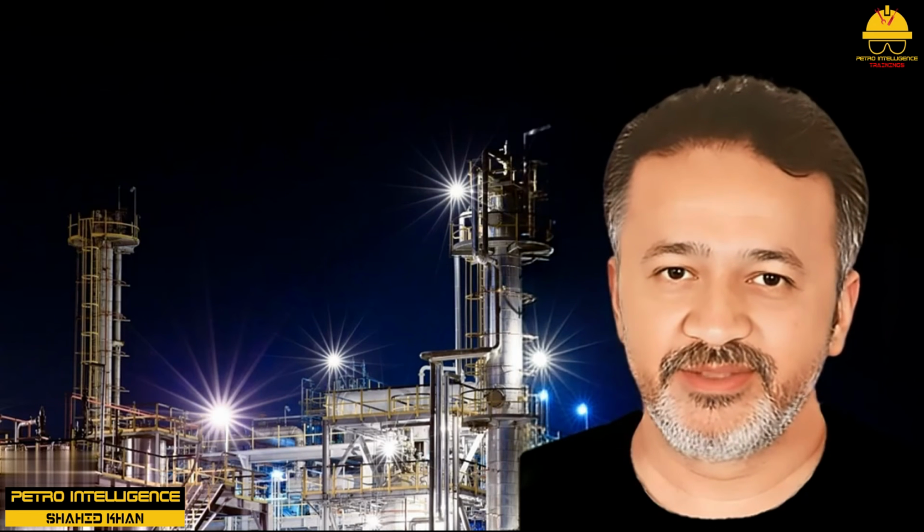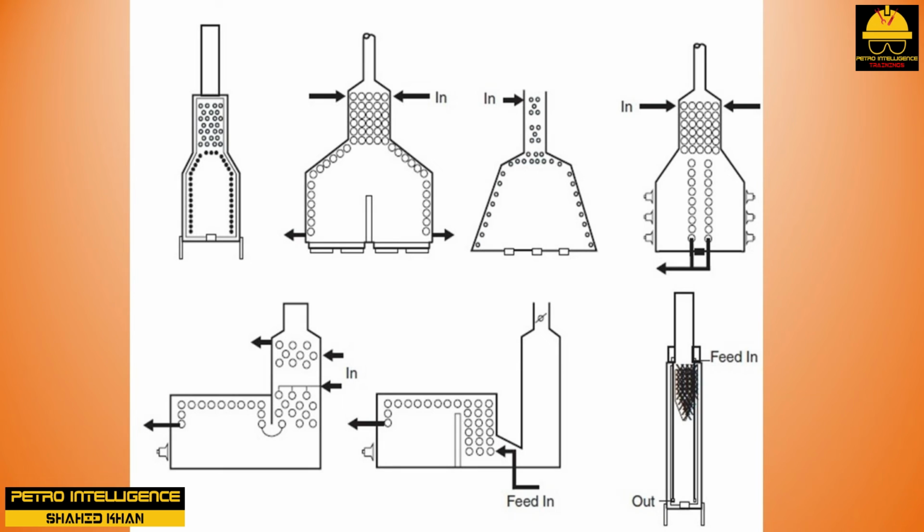Reaction furnaces. Reaction furnaces are simply fireboxes containing an arrangement of tubing through which the reactant stream is passed. A fuel and air mixture is introduced into the brick-lined firebox, which provides the heat for the reaction that occurs in the tubes. Most furnaces are used to crack hydrocarbons.